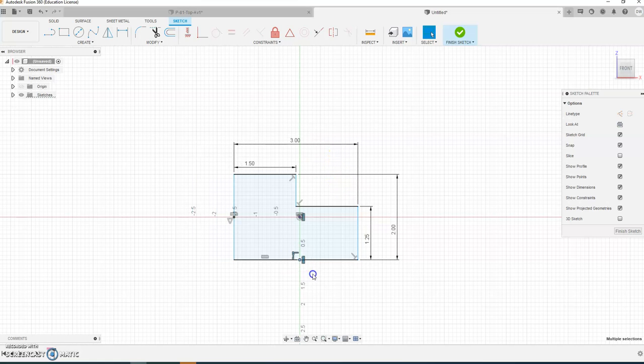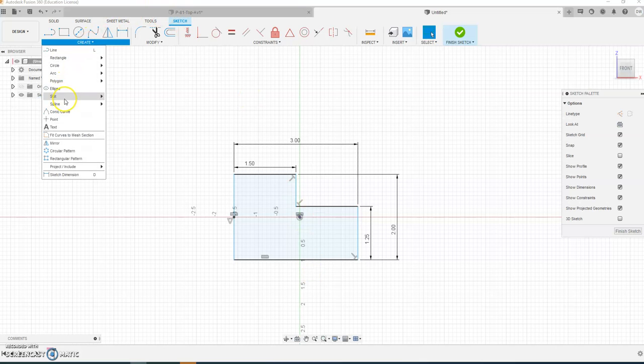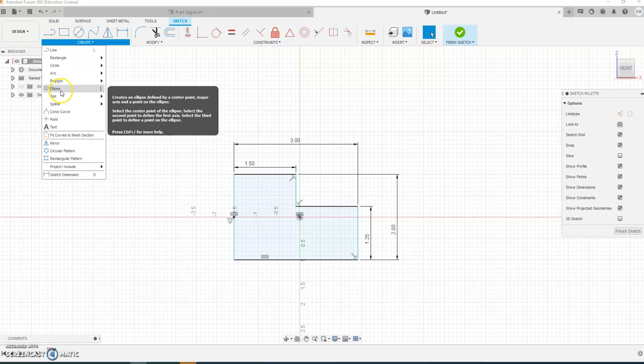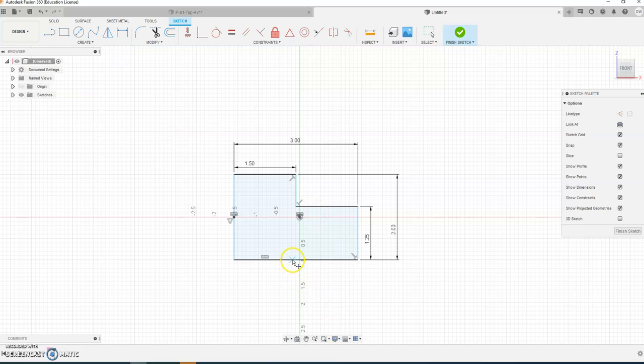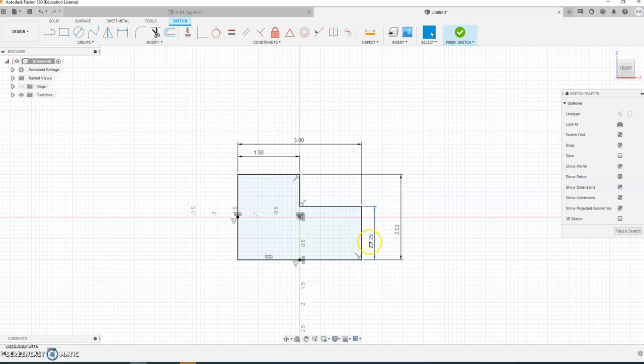Okay, we're doing that. I need to get rid of that constraint there on the bottom, my point constraint. And as you notice here, you just always have to troubleshoot it a little bit. See how it's moving. Put that one back in there at the midpoint and reconstrain this one back. There we go. Now it's all blue. All of my dimensions are correct. We can move these around a little bit so they're a little bit more organized, and that looks great.